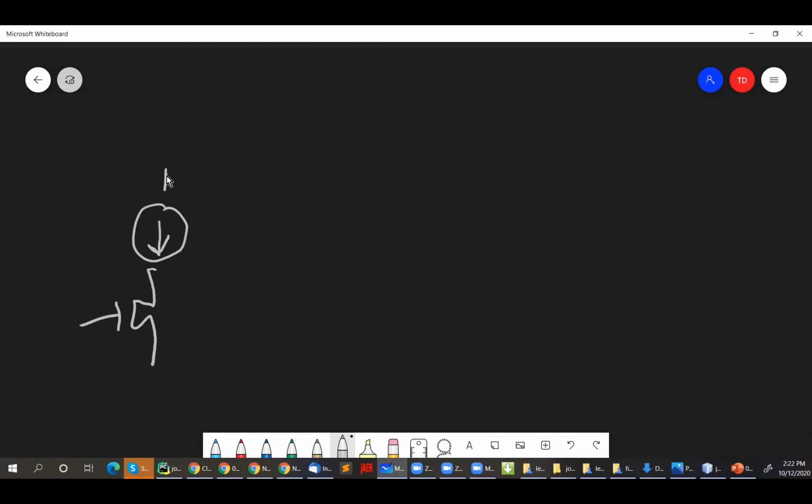Okay, so here's a simple model of an inverter. You have an NFET at the bottom. You're going to apply an input to the gate of this transistor, and then you have a current source at the top, right? Usually this is drawn as a circle with an arrow coming down. Of course, this current source can be provided from one of your measuring instruments, but can also be provided by a transistor, right? So you just have to know where to operate the transistor then. And so then you have the VD here. That means now this is your input, and this would be your output.